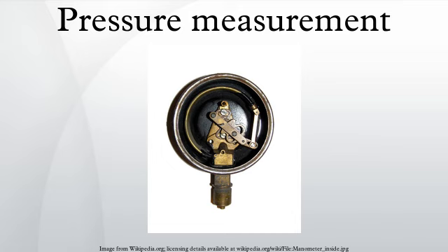The deformation can be measured using mechanical, optical or capacitive techniques. Ceramic and metallic diaphragms are used. Useful range: above 10^-2 torr, for absolute measurements. Welded pressure capsules with diaphragms on either side are often used. Shape: flat, corrugated, flattened tube, capsule, bellows. In gauges intended to sense small pressures or pressure differences, or require that an absolute pressure be measured,